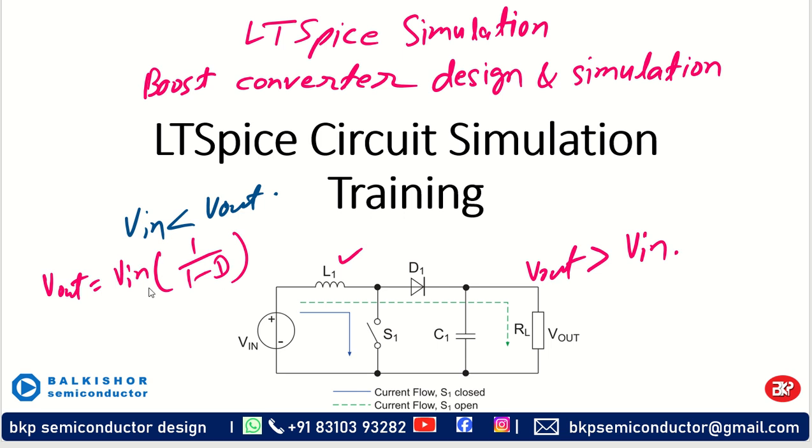That depends on V input into 1 by 1 minus D, where D is your duty cycle, which is T on time divided by the total time period T of the switching frequency of this particular switch.